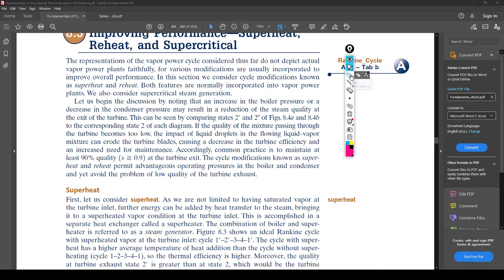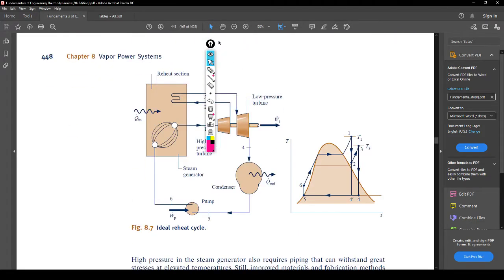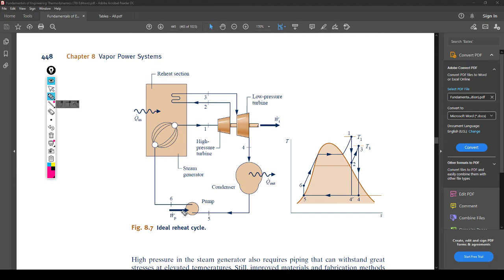Now, a reheat is, as I said before, shown down here. So this is a reheat. If you recall, from the pump into here, this was state 1 and 4 in the other cycle. It was into the boiler, out of the boiler. This was the amount of heat being generated in the boiler, and it went straight into the turbine. But now this is the high pressure turbine, so that's why they break these up. This is the highest pressure in the cycle.